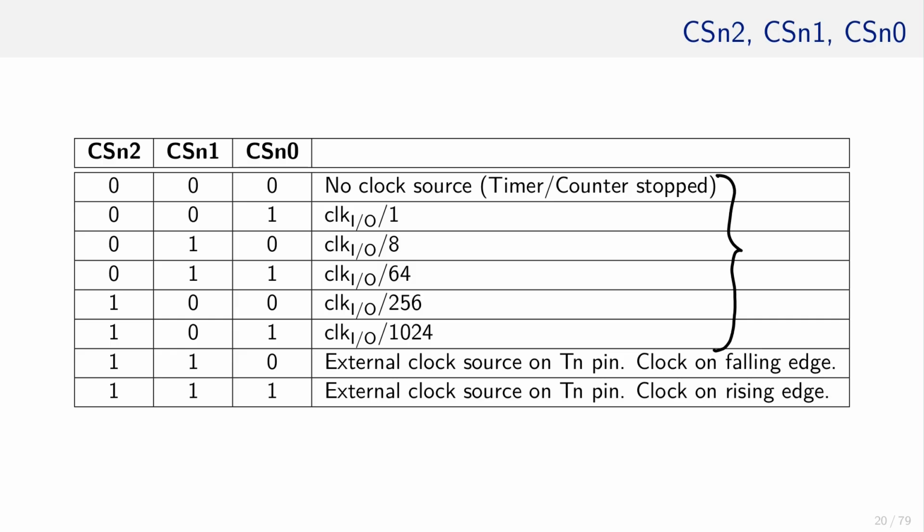Please note, not all prescalers are available for all timers. The same is valid for the edge detector. Not every timer has one. Remember, timer 2 does not even have the pin T2, so no edge detection here, but it has more prescaler settings.